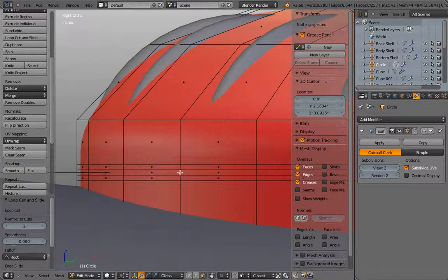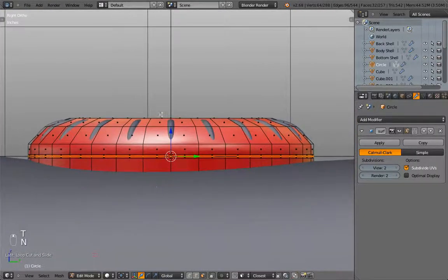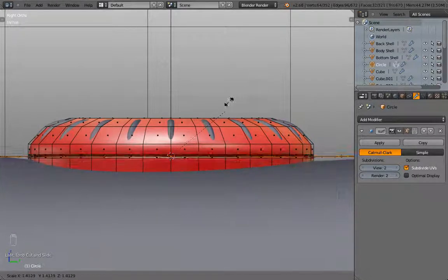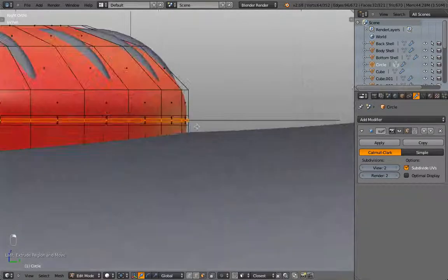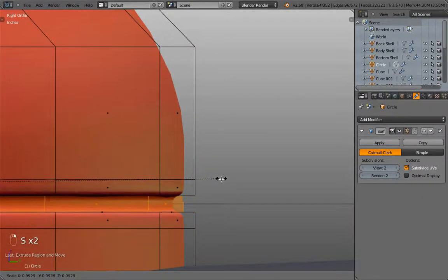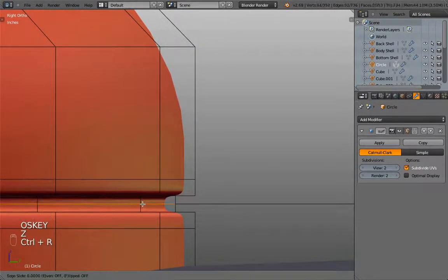And then in edge face mode, Alt click, I select this complete ring. Press E and then S to scale. And then Shift Z because I only want them to scale along the X and Y axis, not along Z. So vertically they stay the same size. So this is actually similar to an offset. And maybe like this, oops, wrong direction, maybe one more cut.